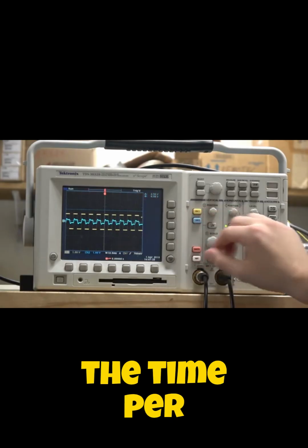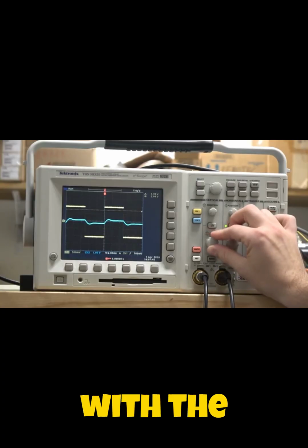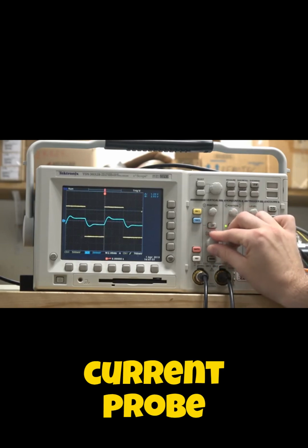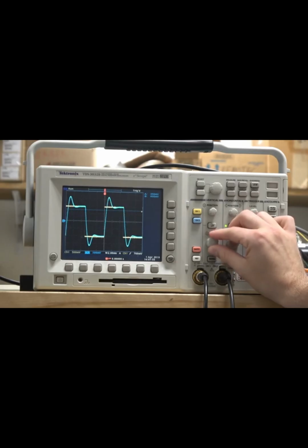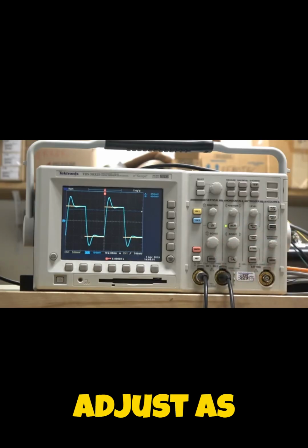When scaling the time per division, 2 milliseconds should be appropriate. The channel with the reference in signal should be scaled to 500 millivolts vertically. The channel with the current probe should be scaled to 100 millivolts. These are only recommendations for viewing the waveforms. Feel free to adjust as necessary.